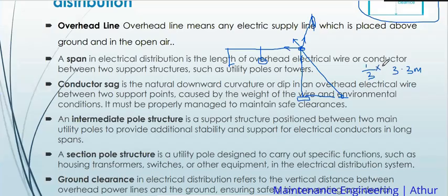Now the height of the pole for secondary distribution, that is low voltage. These poles are always 9 meters, 10 meters, and sometimes when the topography of the area is like a valley, it goes to 12 meters. So when you get 1 over 3 times 10, which is the normal, if it is a flat area, I think you are supposed to get around 3.3 meters.